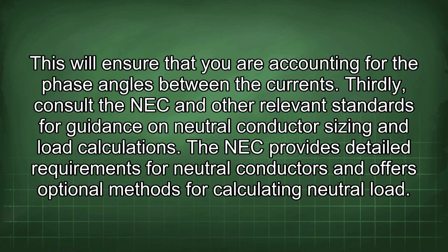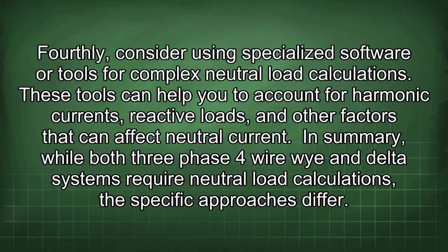Thirdly, consult the NEC and other relevant standards for guidance on neutral conductor sizing and load calculations. The NEC provides detailed requirements for neutral conductors and offers optional methods for calculating neutral load. Fourthly, consider using specialized software or tools for complex neutral load calculations. These tools can help you to account for harmonic currents, reactive loads, and other factors that can affect neutral current.